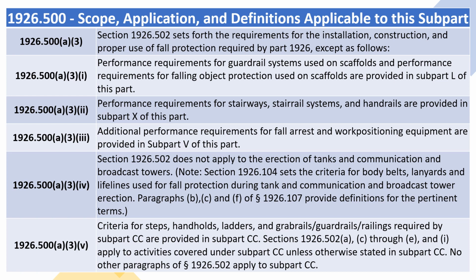1926.500(a)(3)(iv): Section 1926.502 does not apply to the erection of tanks and communication and broadcast towers. Note: Section 1926.104 sets the criteria for body belts, lanyards and lifelines used for fall protection during tank and communication and broadcast tower erection. Paragraphs (b), (c), and (f) of Section 1926.107 provide definitions for the pertinent terms.